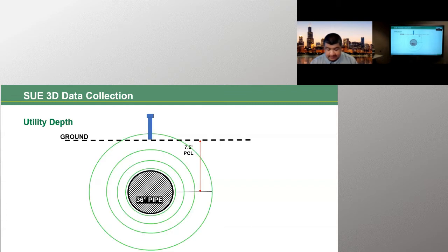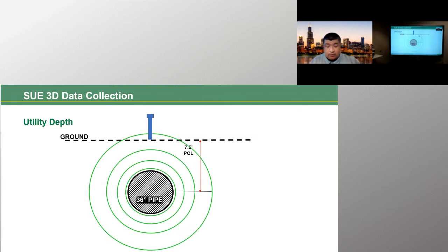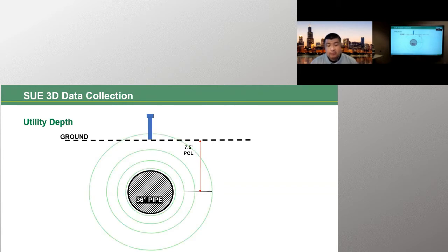It's important to understand that depth accuracy can be affected by several factors though, such as interference from nearby conductors, which invite signal distortion and or bleed off. Soil conditions and poor utility installation methods, such as improper grounding, can also influence the accuracy of the electronic depth as well as distinguishing its horizontal positioning.